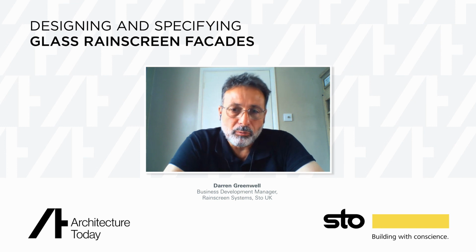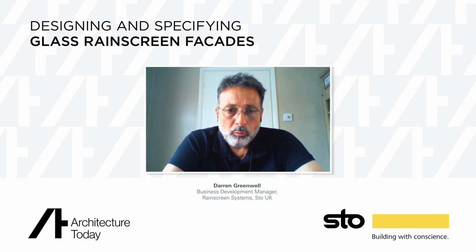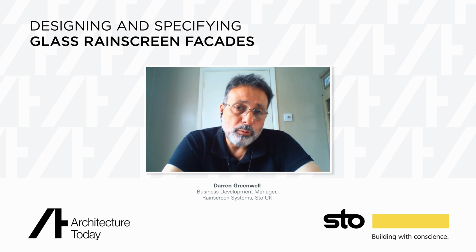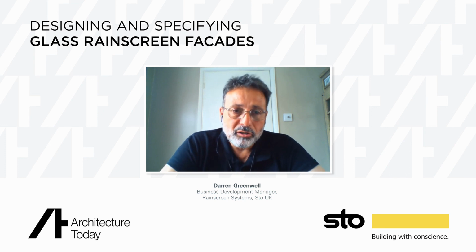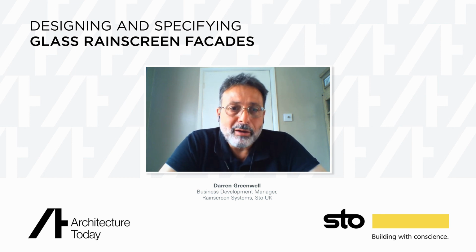So it's absolutely critical that we work early with the architect to understand the forces and the dynamics that are acting on the building. We will either engage with the appointed engineers to obtain a wind load calculation report, following which, as Greg alluded to, we'll process that through our own sub-construction calculator in order to define the centres, the brackets, the spacing, the quantities, in order to make sure that system stays on the wall wherever it may be.